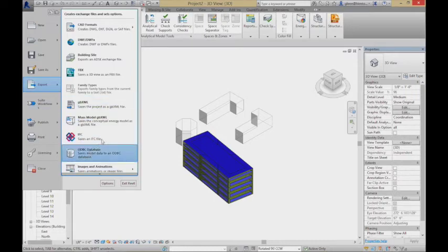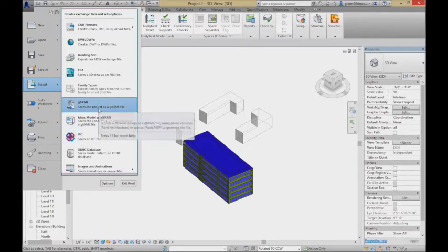I think someone said IFC, probably. IFC is a format. IFC is a kind of very international foundation class format. It's good for getting things across to a number of even CAD packages or just BIM modeling packages. Okay. So it really depends on which format they'll take. Okay. Another format that some people like is GBXML, although that's more of an Autodesk format.